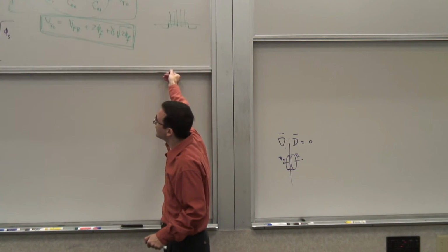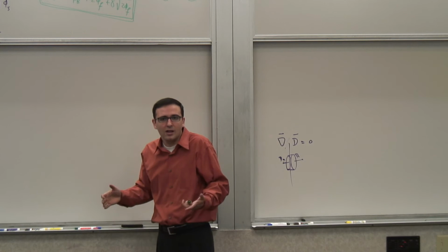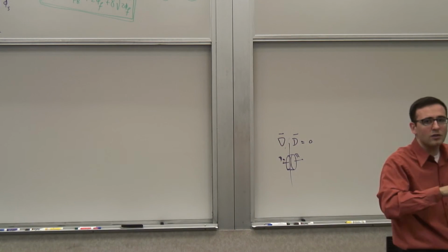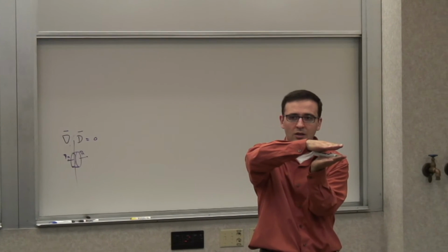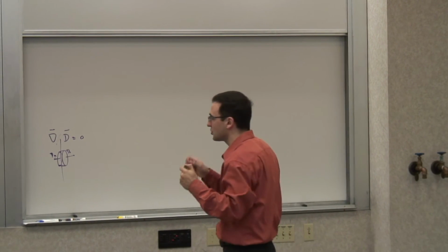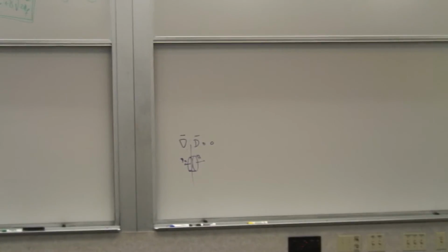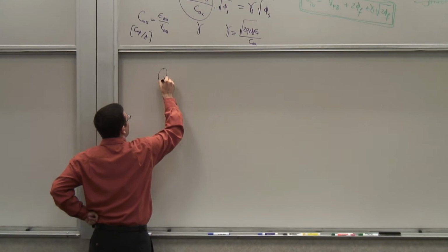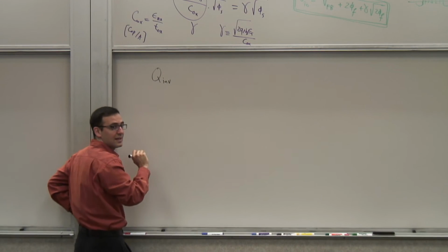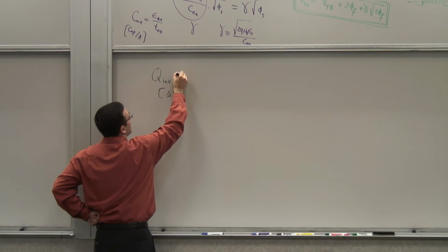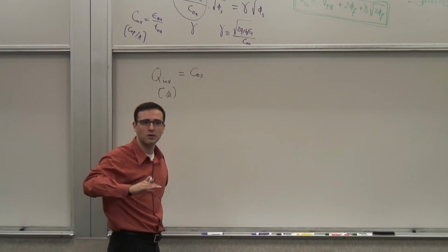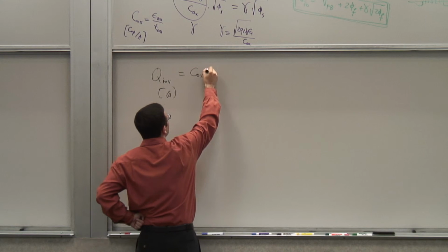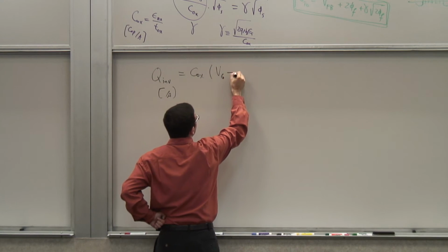So, what can I say about the surface charge density? Beyond this, I simply have a capacitor, right? If I ignore all the charge I've accumulated up to this point, which is not large, then beyond that I have a parallel plate capacitance. So what is the strong inversion charge I will induce on the surface if my Vg were above VT0? The Q inversion, per unit area, is Cox, a capacitance, except that it has a certain offset voltage, a threshold voltage that needs to be met first before you get the extra voltage to induce additional charge. So it's Vg minus VT0.